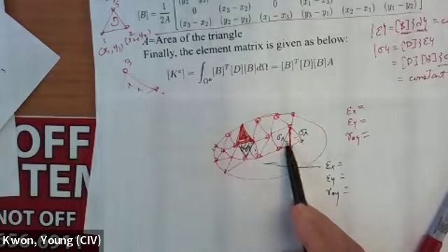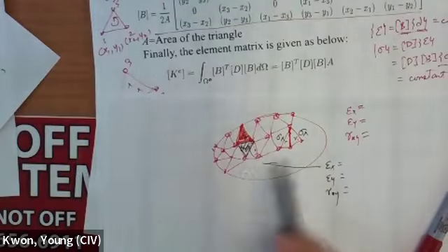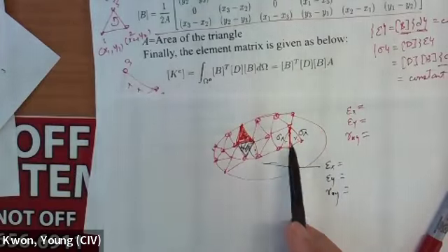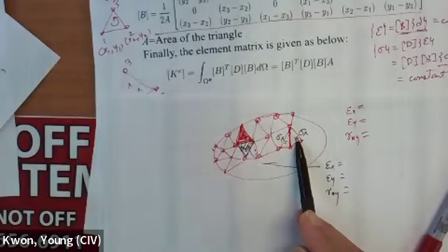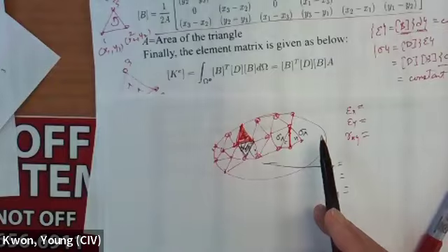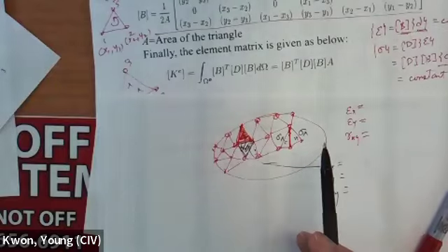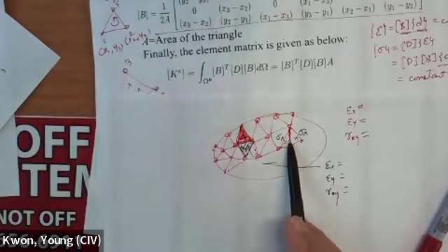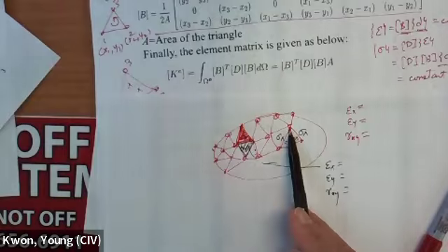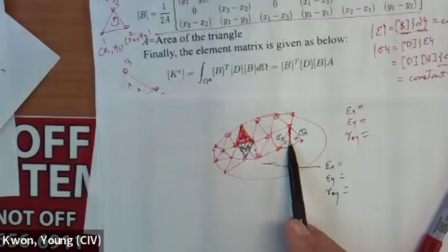This element and that element have two different values in my finite element calculation. Here, let's say 1000 psi. Here, I have 1200 psi. So different. Then it is not correct, because at this interface you have to maintain equilibrium. That means the stress on the left side and the stress on the right side have to be equal to each other, right? That's the right solution.